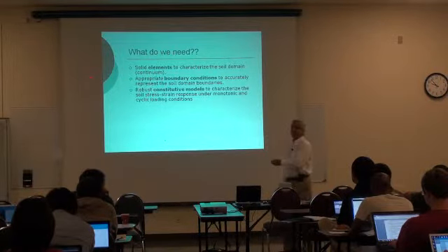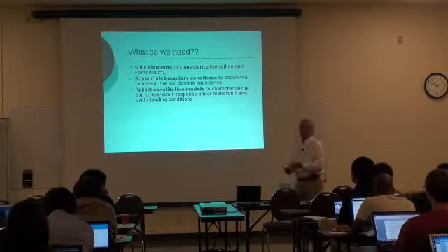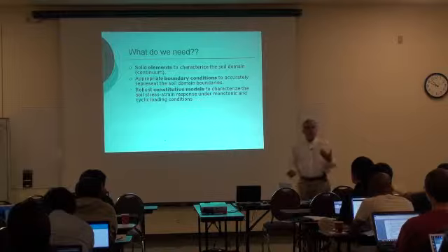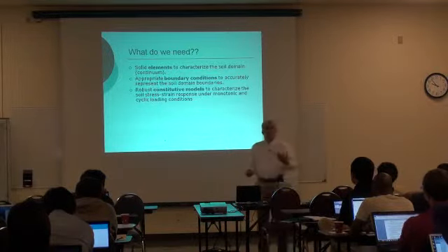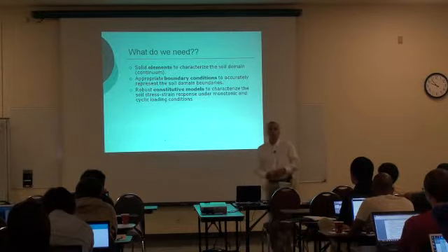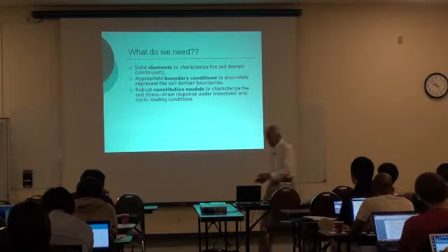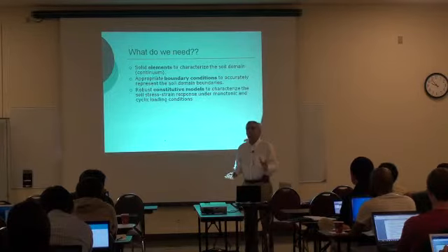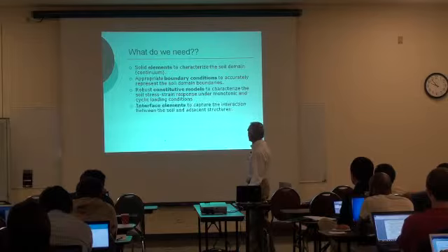We need robust and also efficient constitutive models to characterize the very nonlinear stress-strain response of soils under monotonic loads and also under cyclic loads. A lot of models are only useful for monotonic loads. Some models are useful for both, or only for cyclic loading. This is a big issue because soils are very nonlinear and present characteristics that are difficult to characterize.